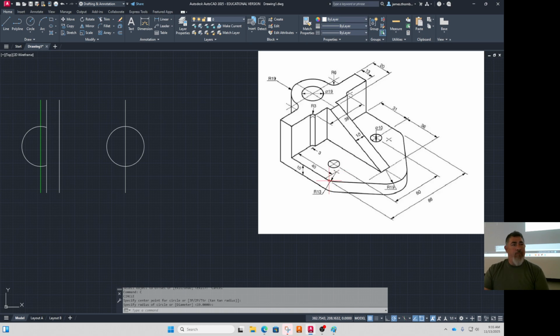If I knew the sharp point, then I could just draw the line sharp and use the fillet command, right? But since I know the center of it, I'm probably going to need to draw that circle first, and then draw a line that goes between those two arcs. What kind of a snap am I going to use for that? Tangent. And then this circle connects to this line, which goes there, right? So where is this corner? I need to come 40 out from here.